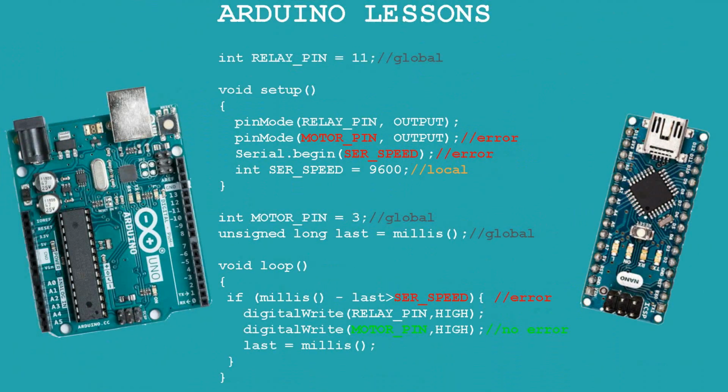And now let's sum up the material covered. Variables must be declared in the program text no lower than the expressions in which they participate, only higher. Local variables are used only inside functions and inside for loops and others, while global variables can be read and changed in any program function. Local variables have short-term memory, only for the duration of a single function execution. But local variables with the static prefix retain their value until all the controller's RAM is cleared, just like global variables.